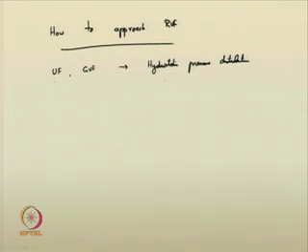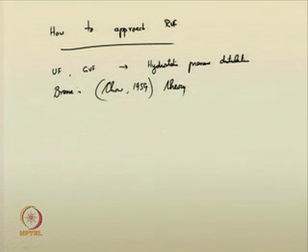The theory which suggested parallel flow or hydrostatic pressure distribution was formulated long back by Bresse, as stated in Ven Te Chow's 1959 book. This is called Bresse's theory, the concept of parallel flow or taking hydrostatic pressure distribution for fluid flow. That Bresse's theory is not valid for rapidly varying flow.